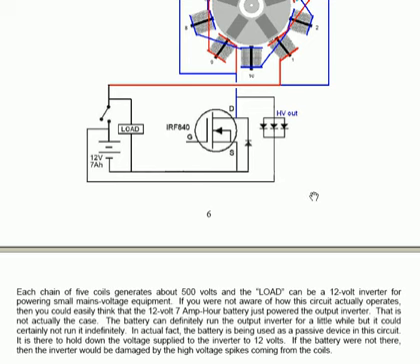The FET transistor is very much like an NPN transistor. The gate, which controls it, is like the base. The drain, which handles the large heavy-duty current, is the equivalent of the collector, and the source, S, is the equivalent of the emitter on an NPN transistor.